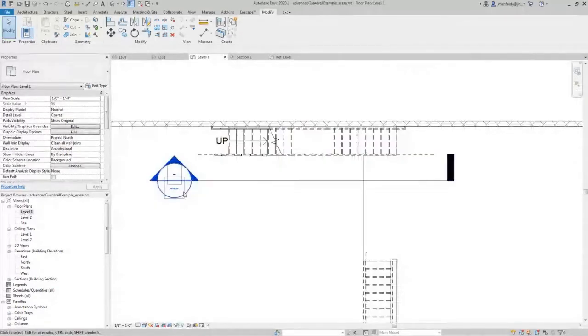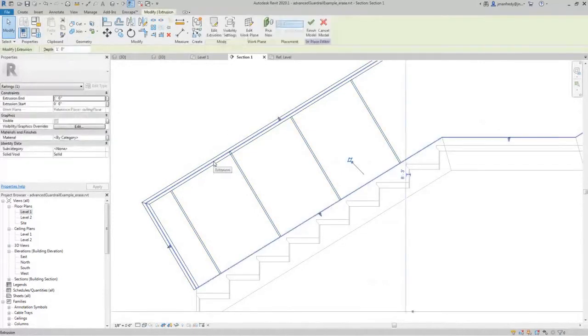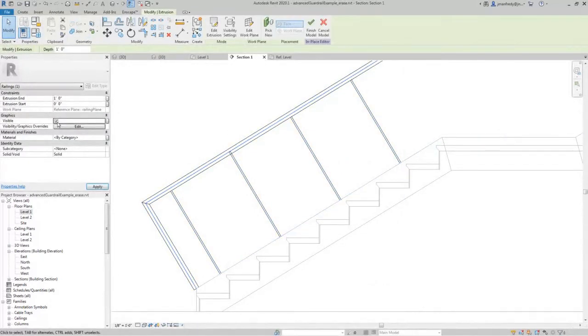Let me go back. Let me go into here. Let me edit this model. Let me grab this wall that was invisible, make it visible this time. And for the thickness, I want to make it, say, 1/2 inch of glass. So 1/4 inch thick in one direction and negative 1/4 inch thick in the other direction. So this is going from the center line out a 1/4 inch and toward me 1/4 inch. So together the glass is going to be a 1/2 inch thick.